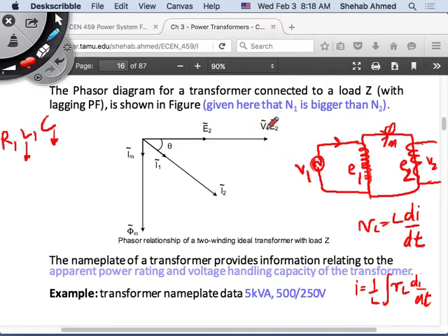So this is actually my V1 voltage that I've placed here, right? And since I ignored any impedance here, this V1 is also equal to E1. There's another typo here. Okay? This V1 is also equal to my E1 here. They're equal. There's no impedance between them, for now. So I put V1, which is in this case equal to E1. But the consequence was current was flowing in the core, and this current created some magnetic flux that was flowing in the core. Hence, the current that resulted was 90 degrees lagging from the voltage that created it, because I'm creating flux, storing energy in flux, meaning I have an inductor representation.